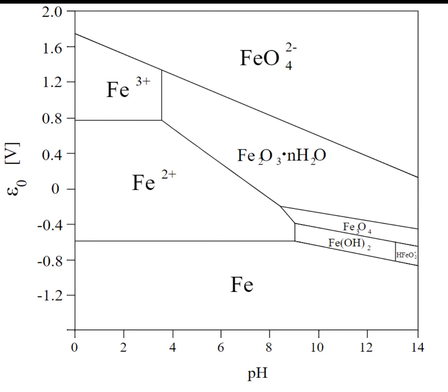So if we do that experiment, which we will do, take some iron and increase the potential, what we would expect to see is no current flows until we get up to here. Then we can make iron dissolve, and it will dissolve fairly quickly because there's nothing stopping it. Then it'll suddenly drop down. Then our current will go low as we increase the voltage until we get here, and then we'll suddenly generate current again.